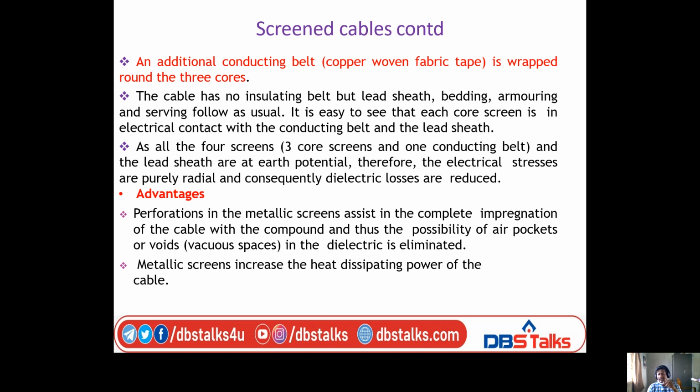That means core screen, that is metallic screen, is in electrical contact with conducting belt and also lead sheath. All the 4 screens, that is 3 core screens and 1 conducting belt, and the lead sheath are at earth potential. That means all are in contact with earth potential.